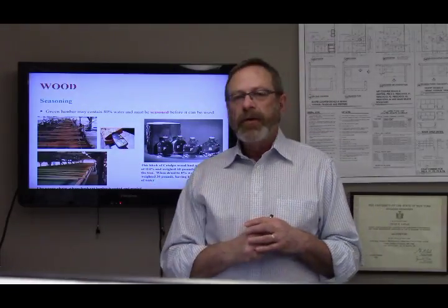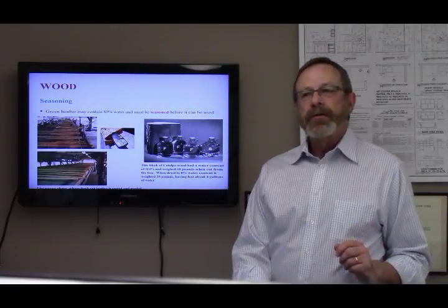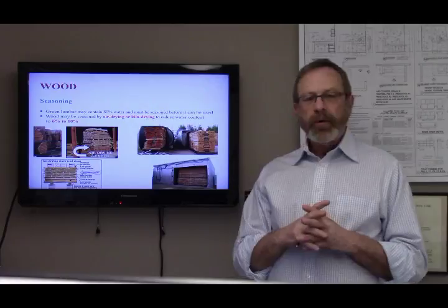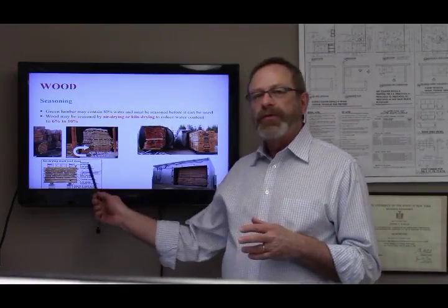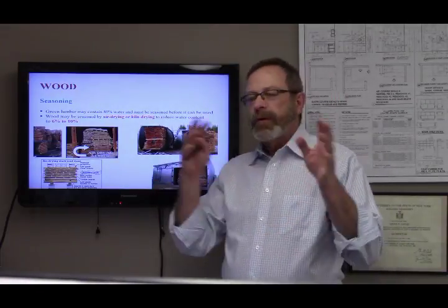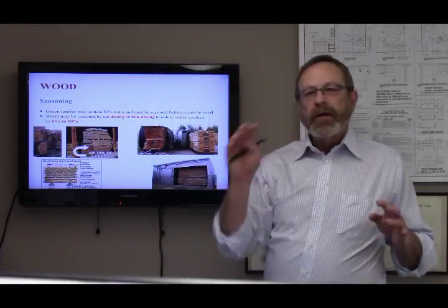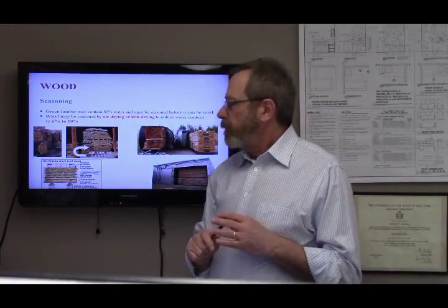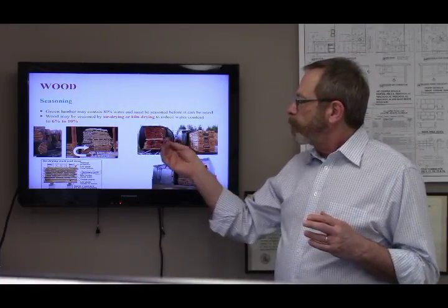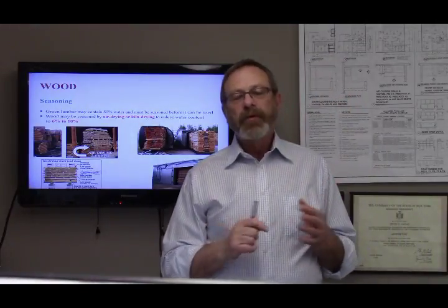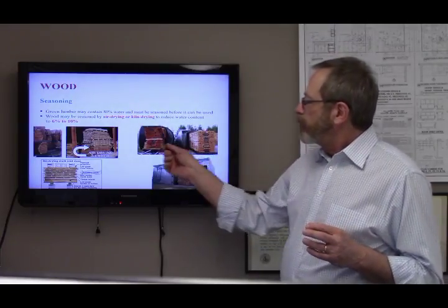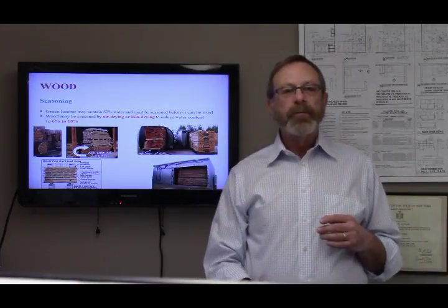This is a meter. They are measuring the water concentration in that piece of wood. The two processes for seasoning lumber are air dry, where the wood is stacked with gaps left between each individual piece, and the air simply circulates under a sheltered area, and it will eventually dry to the specifications of the mill. Or it can be sped up and dried in a kiln, similar to a type of kiln you might use to dry pottery in advance of putting a glazing on it. So it's a similar situation, but it's an accelerated process.